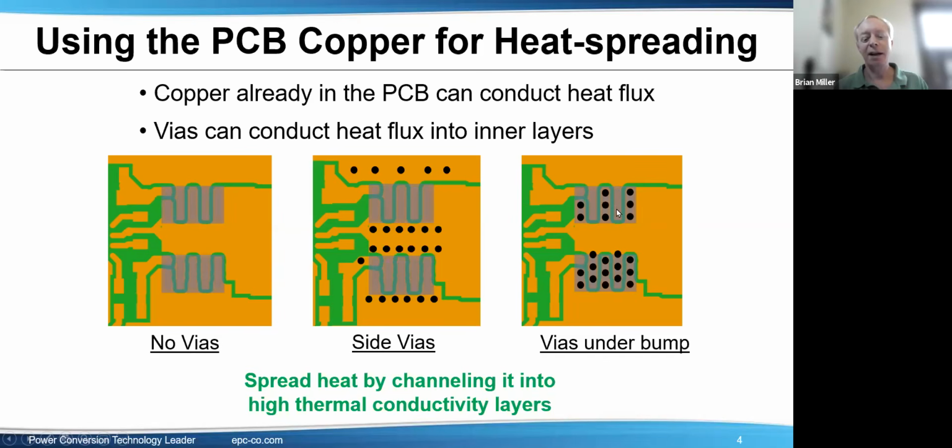So in a lot of cases, you wouldn't have vias there. So you'd have vias on these. And you can see there's a limit to how many you can have just before you get to interfere. You want current to flow down this copper to the rest of them. So it's really a board layout kind of question. But yeah, the more the better in terms of heat flow, but that's not always true for the electrical design.